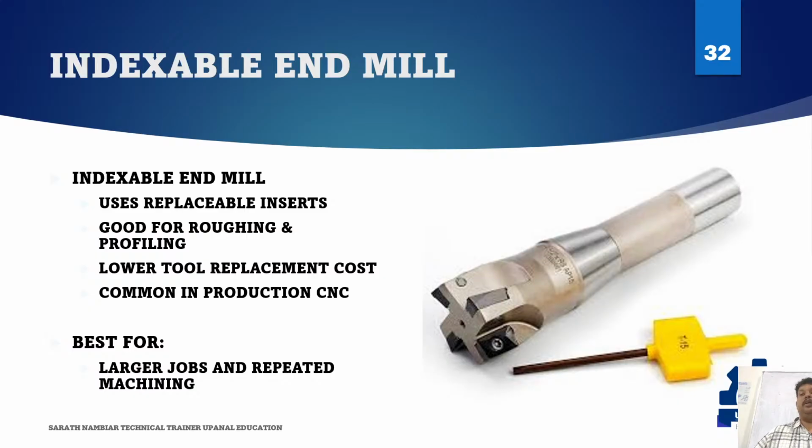Indexable end mills are commonly used for roughing, profiling, shoulder milling, and general material removal. They are strong, practical, and popular in industrial environments. Now remember, they may not always replace small precision solid carbide tools, but for medium to heavy machine jobs, they are highly efficient. This is a classic example of modern production thinking, modular tooling for productivity.